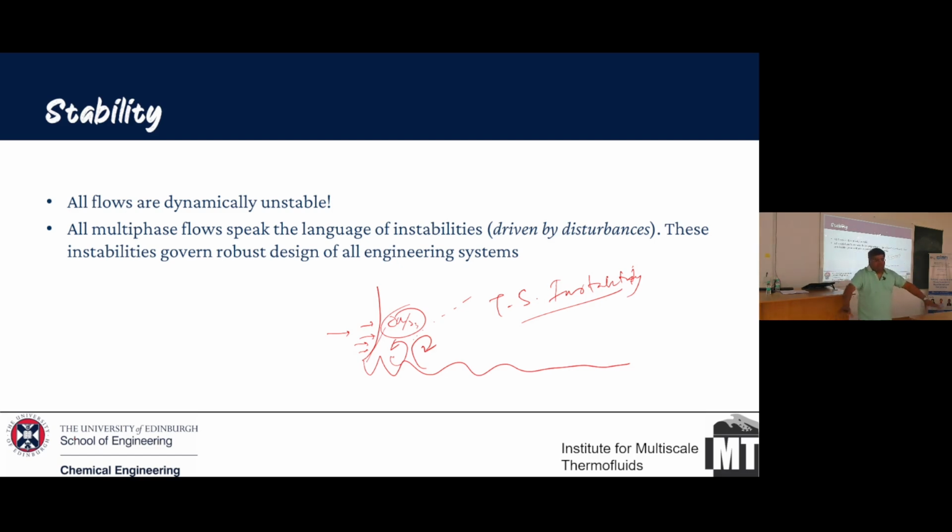In most laminar flow, in your microfluidic devices, the Tollmien-Schlichting instability is too small, so we ignore it because it is not creating turbulence. But if you have a larger system, if you want to construct a smoothish pipe, this is what is going to play a role. In fact, in Manchester, people have created a smooth pipe which shows laminar flow at a Reynolds number of 6,000. That is an ultra smooth pipe. Obviously, practically, we don't need to make it, because everything has roughness.